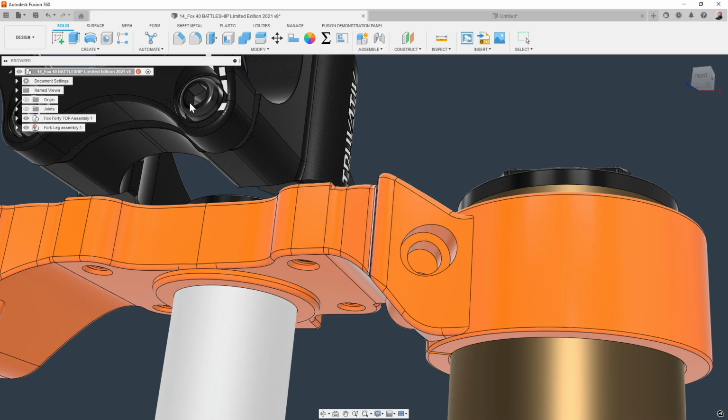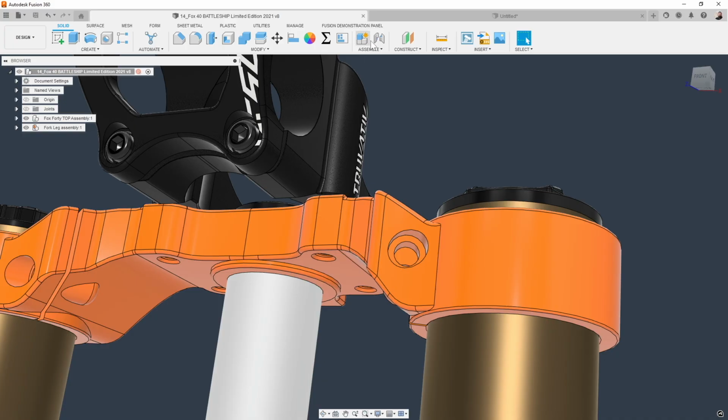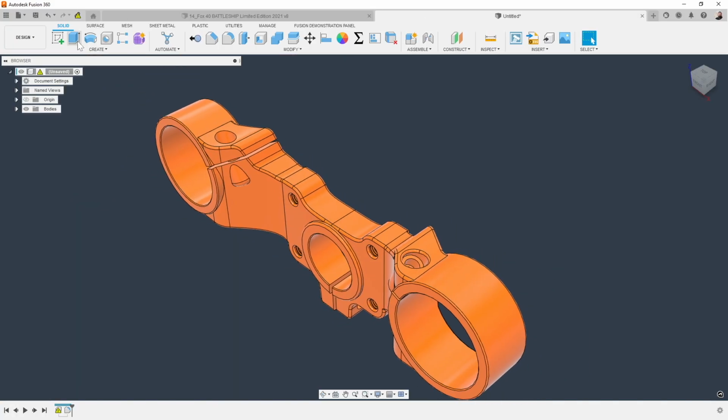So we see there's nothing here in the original file telling me that something's been changed, right? Because technically nothing has. But I did just update the original file here. Now in my Derive, we can see that it is now out of date. And when I click on this, pay attention to what happens in my fillet. My hole is going to move, but my fillet or my modification will stay there once it updates. And now you can see it moved.